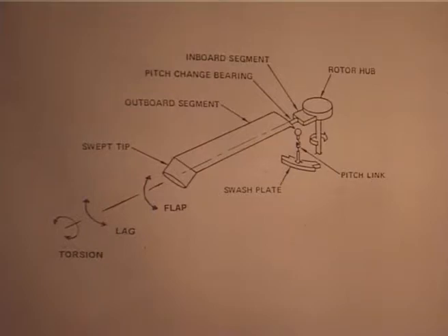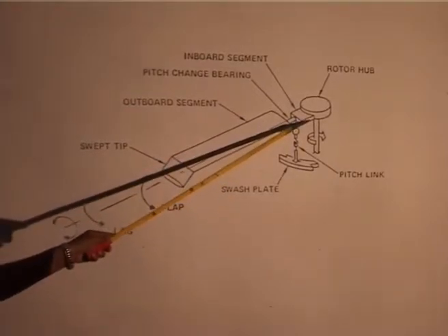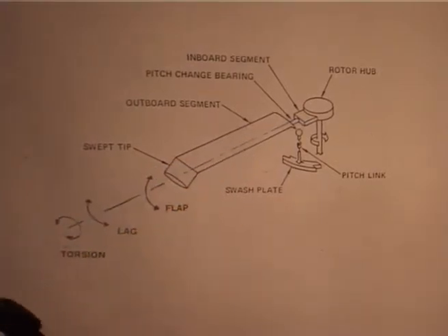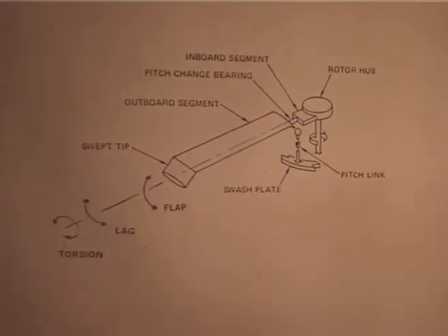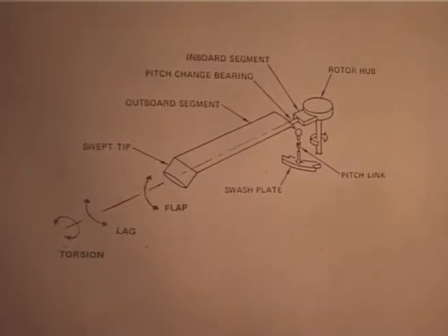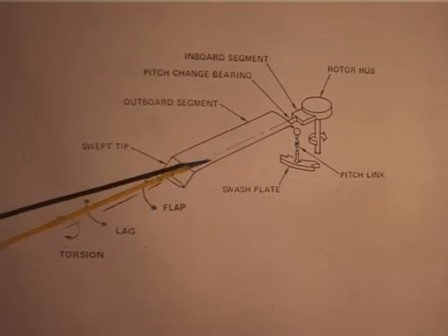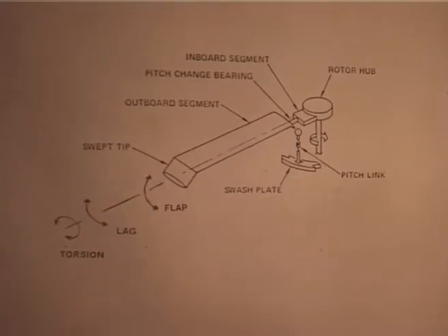Okay. Pitch angle you change at the root of the blade, but the blade also can twist elastically. Okay. That is equally important when you are analyzing the actual blade, because your angle of attack changes. Now, this is a large aspect ratio, in the sense usually it is about 20-25 feet.